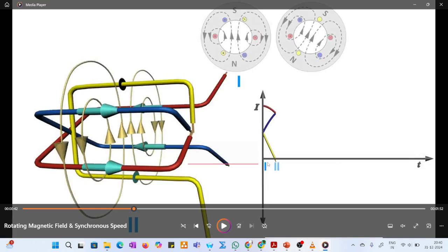Here we have the windings; we can consider the six windings as R phase, Y phase, B phase. Each is placed at a 120 degree phase shift. We can see that in each one, current is flowing in and current is coming out. The plus sign indicates that current is flowing through, and the dot point indicates that current is coming out.